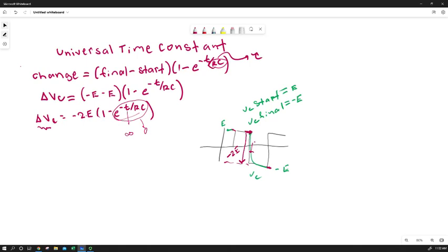When our measured voltage drop over the capacitor, which we bring in on whatever channel of our scope, reaches that value, we know that it corresponds to t equals tau equals RC. We can make that measurement and then see how it corresponds to whatever resistor or capacitor we've chosen, and maybe even identify which one of them if we know the other.